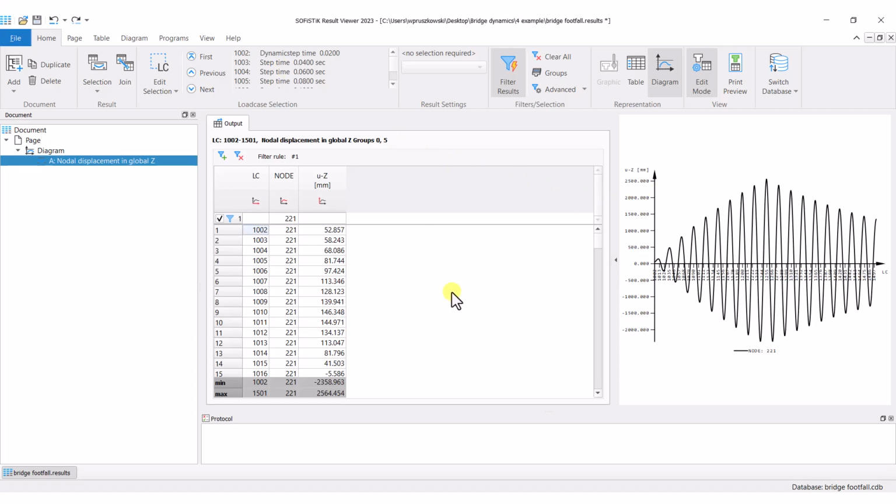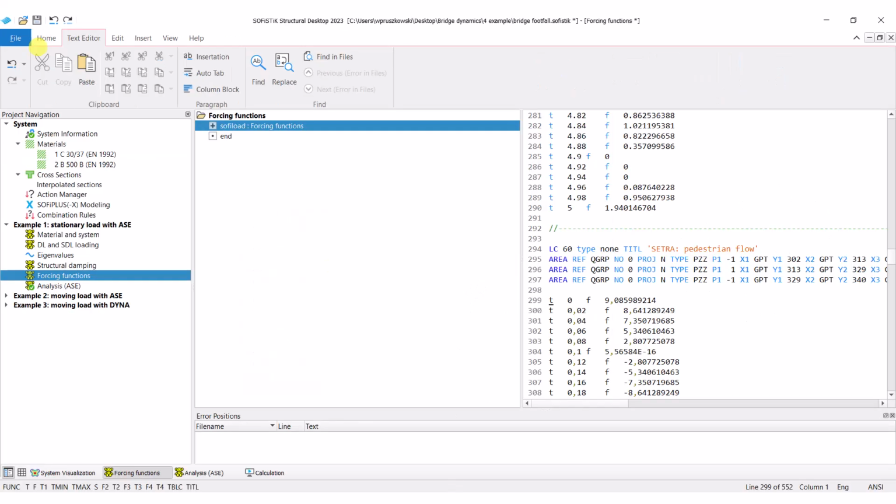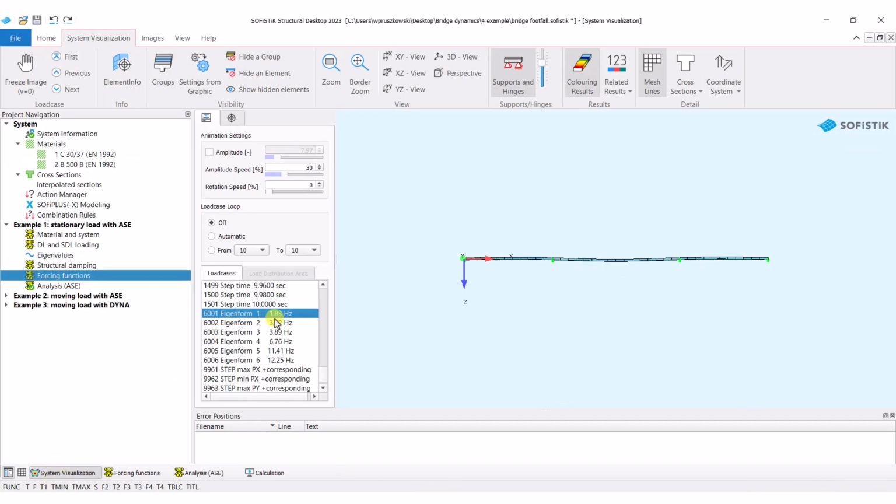Let's use this opportunity to highlight the dangers of external loading acting with a frequency matching the natural frequency of the structure and thus causing resonance. These midspan deformation values have been caused by the central loading model acting in tune with the structure's first harmonics, so 1.83 Hz.